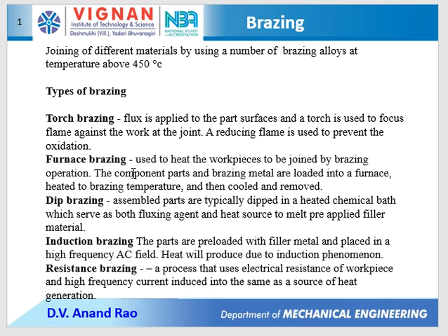And next one is dip brazing. In this, assembled parts are typically dipped in a heated chemical bath which serves as both a fluxing agent and heat source to melt pre-applied filler material.